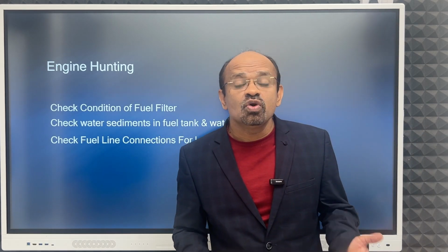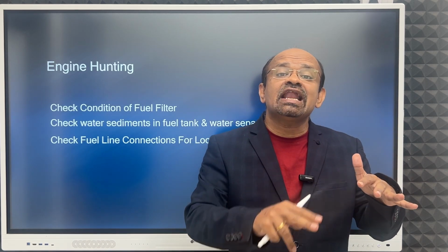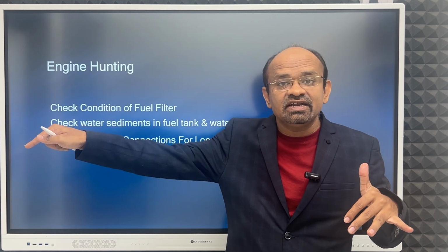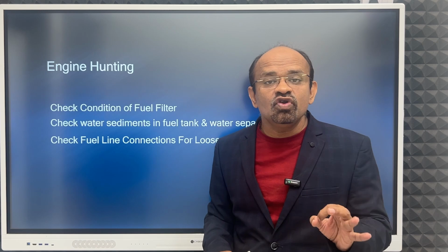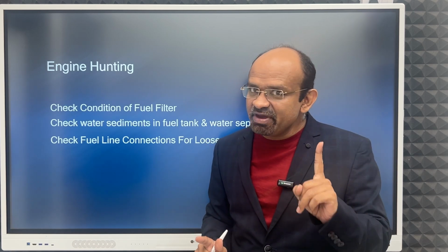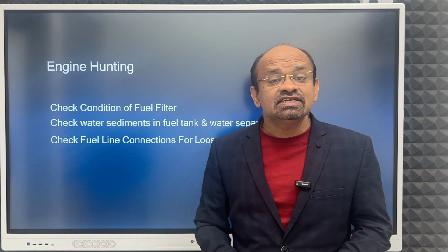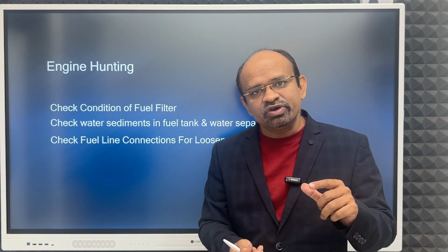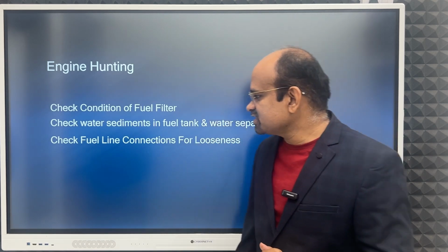I just told you, just check if the water separator is full, and that is why it is allowing water to go inside the fuel line and ultimately into the engine. So it should not happen. Check the water sediment. If it is full, just check. Remember, I told you, first thing you need to check is this water separator, for the sediments and water. You need to remove it so that there will be space for further water or sediment collection.